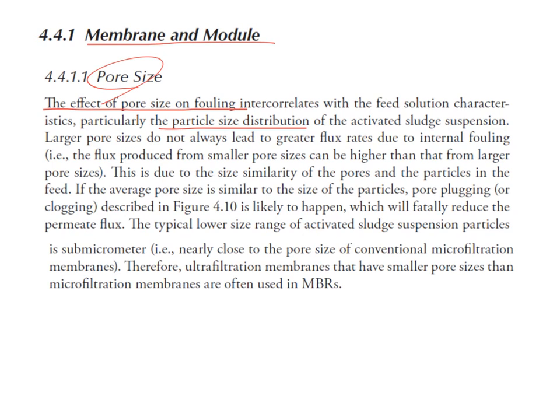So if we have foulant in the feed solution with a size similar to the pore size, we will experience pore plugging problems. So the relationship between particle size and pore size is very important.